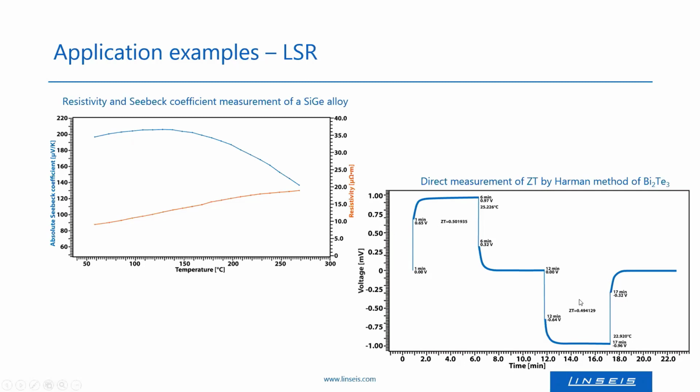So here one can see that they're nearly the same, and on average something about 0.5 for bismuth telluride. And this measurement was performed at room temperature. So for a temperature-dependent measurement, one would need to repeat this measurement at every desired sample temperature.